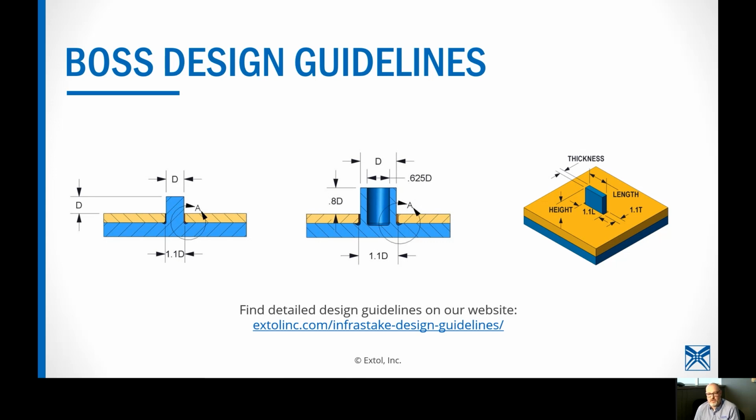InfraStake, being a little bit unique in the industry, we do like to see a recommended design. The question came up earlier, can we do solid bosses versus hollow? Yes, we can. For solid bosses, we would prefer that the height is equal to the diameter. It's a 1-to-1 ratio. When you get into hollow, we like that to be like a 0.8-to-1 ratio.